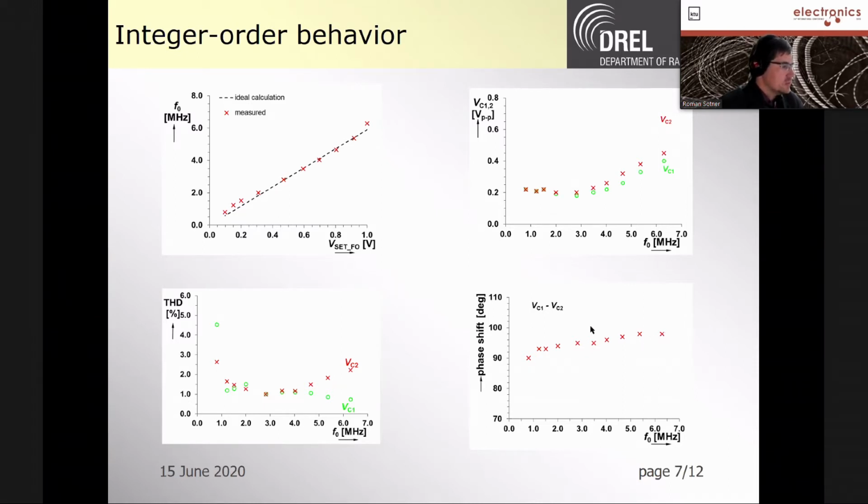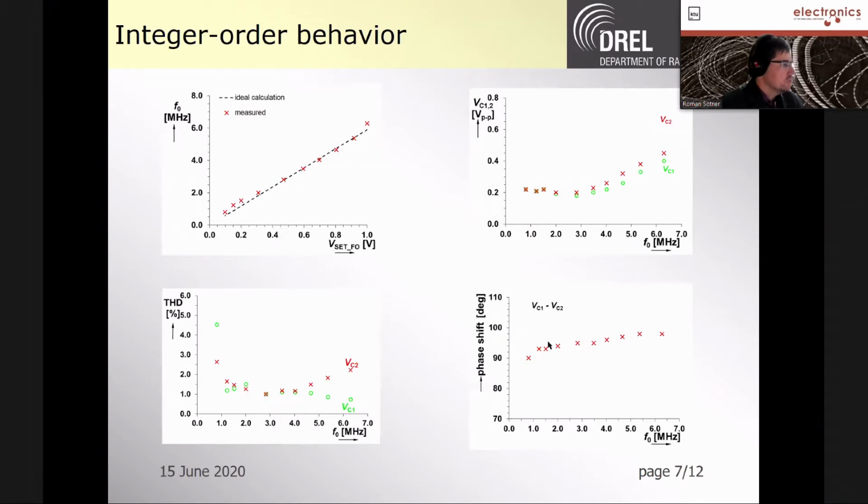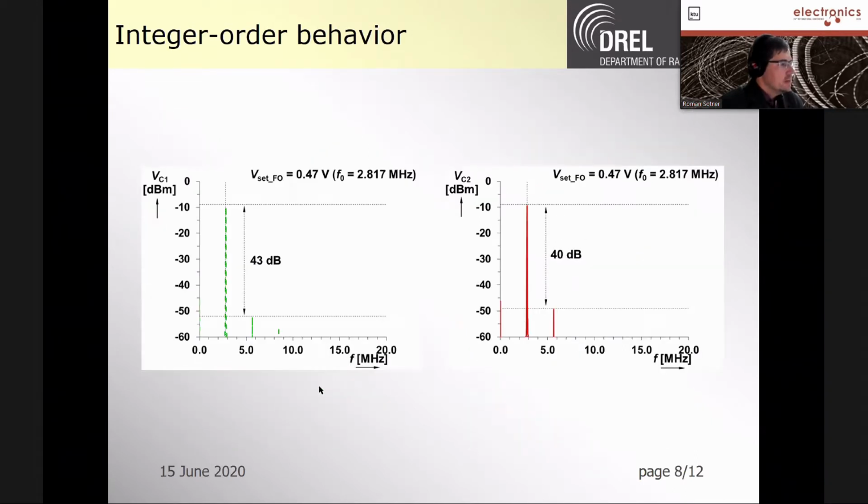This is, I think, a little bit influenced by parasitic influences and the finite bandwidth of the used active devices. There are typical examples of the output spectral analysis. We can see that suppression of higher harmonic components is more than 40 dB. It really corresponds with these results in the middle of the bandwidth somewhere. This is a test example of this analysis for some specific tone.